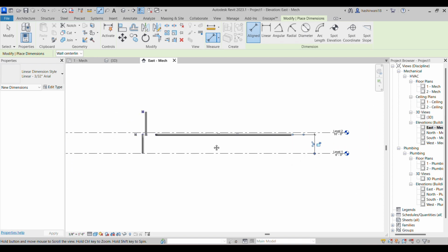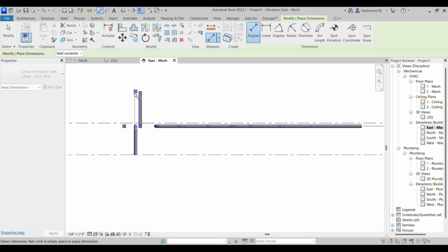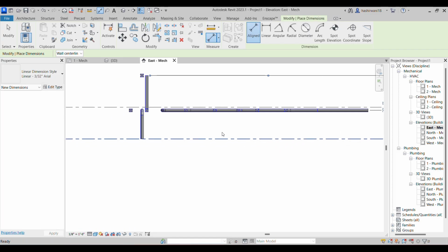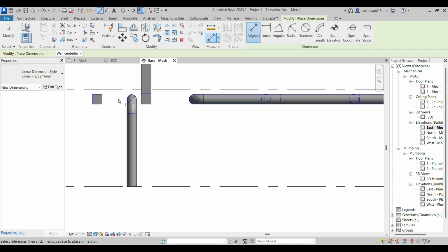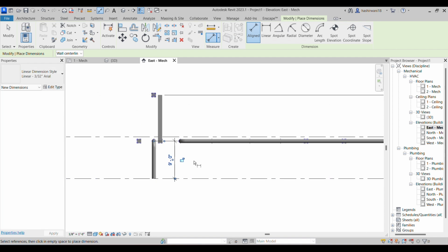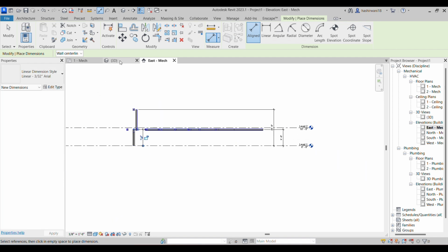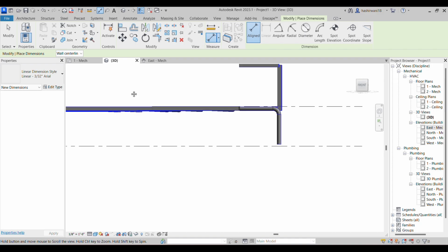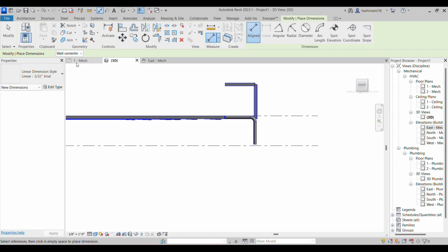And then we also created a stub up. Let's check the height, exactly at 20 feet, right? We also created a stub down to 0 feet, right? We moved it down 9 feet. So by this you can draw all the ducts and get comfortable with this.